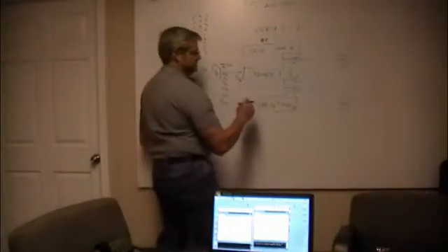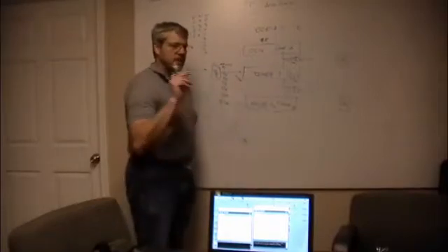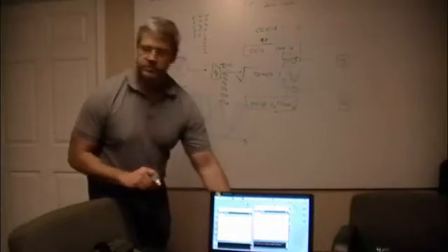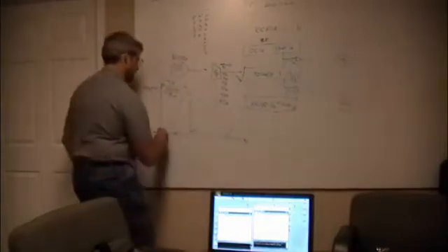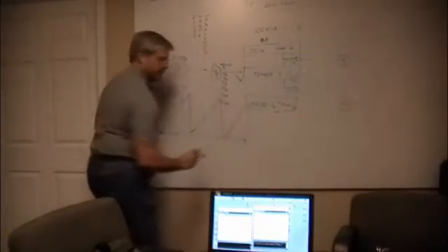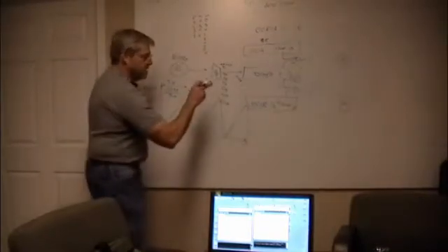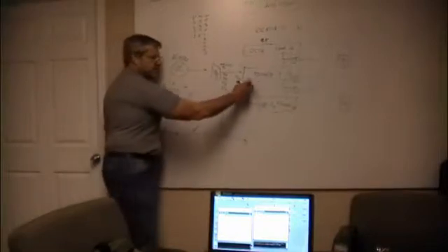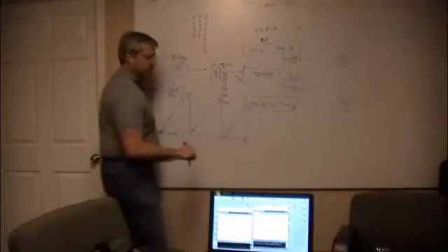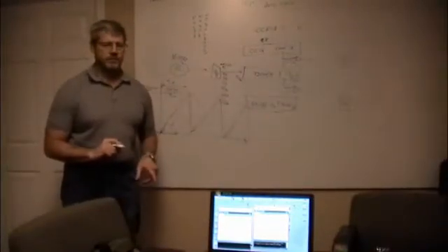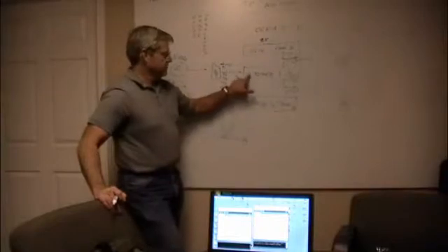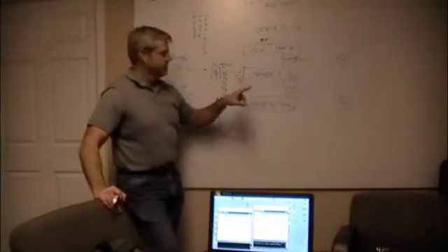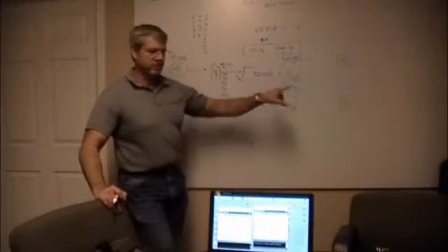The next thing you can do is you can say, I don't toggle. You can choose a mode, and one of the modes that you'll use most often is you'll say, when the timer 1 is less than this value, I want the pin turned on. When the timer is equal to or greater than this value, I want the pin turned off.